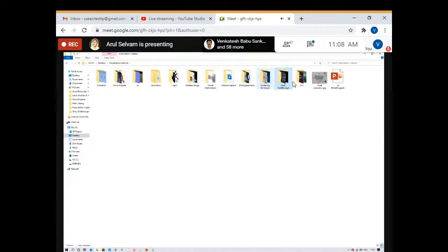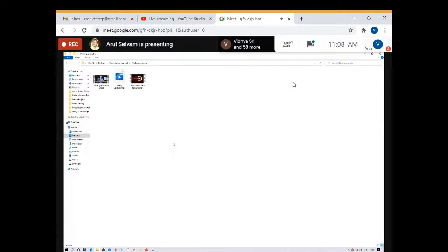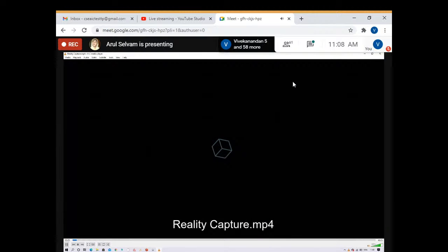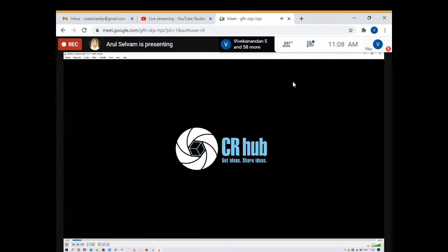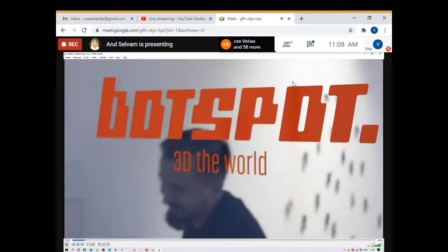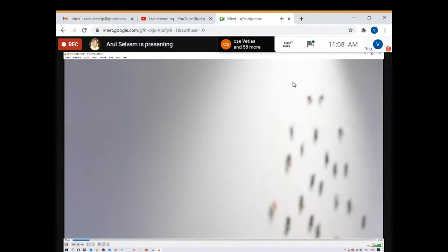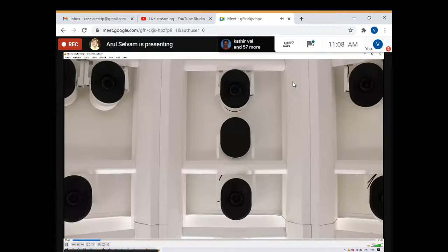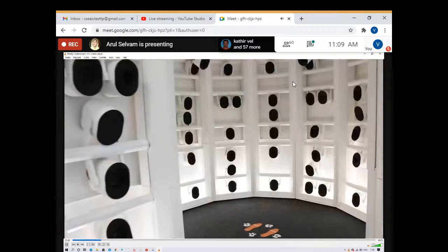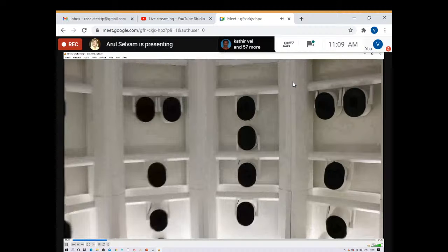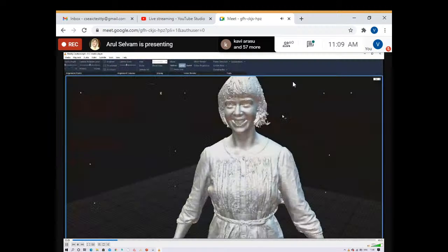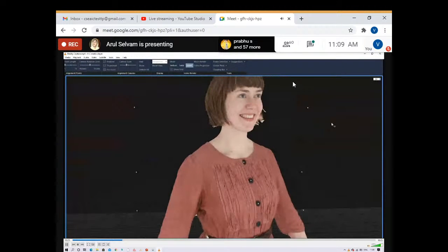And rendering technique. Photogrammetry is another technique used in the industry. For 3D modeling, either the traditional way they do it from the box, or nowadays they use photogrammetry, reality capture. They use multiple cameras at multiple angles and capture simultaneously, and using Recap Pro from Autodesk or any other software, we stitch all the images together and create a mesh. It is something similar to creating a panoramic image, but here we create a 3D model.